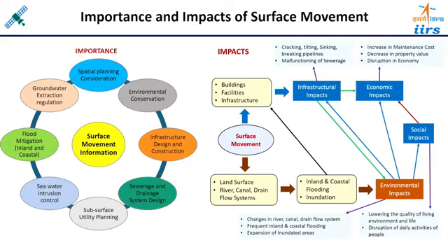As I already mentioned earlier, we can monitor the time series of displacement from differential SAR interferometry or some advanced multi-temporal InSAR technique. If you have the time series of the displacements, then from that displacement we can calculate the velocity, time series velocity, and from velocity we can calculate the acceleration. If we have these kinematic variables, it means we can understand the total kinematics of that particular region. So this kinematic calculation can be done with the help of InSAR technology.